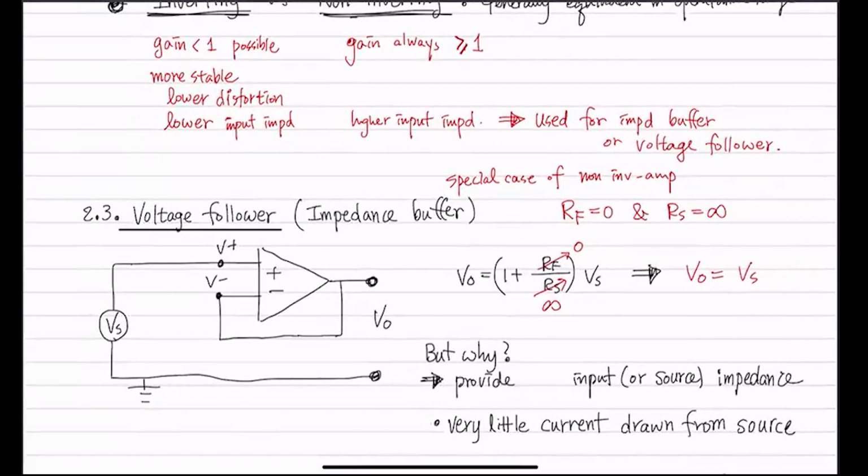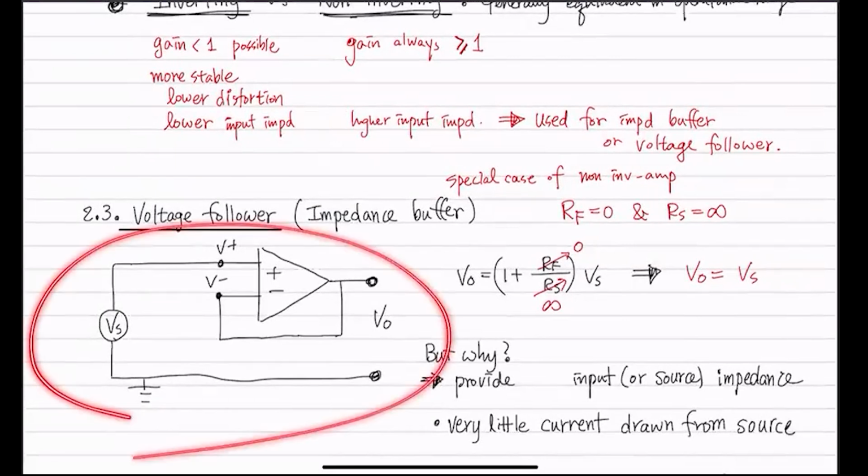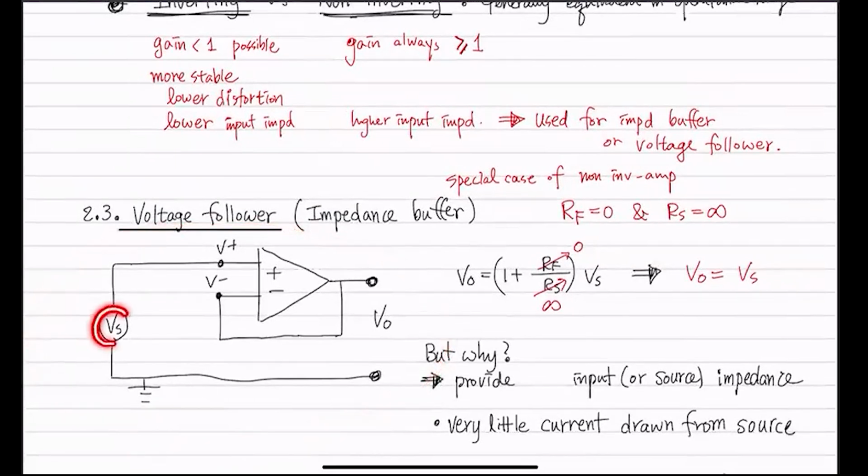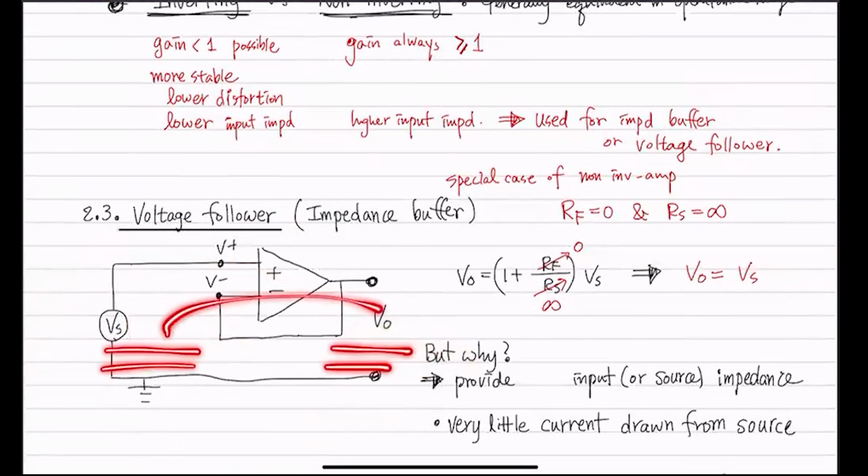So this circuit is nothing but doing, you have your source signal, and then it's just passing it out to your output. If you have a 1 volt sine, it's going to have a 1 volt sine coming out. It's not amplified or shrunk down. It's just passing it the same. So it's called the follower.